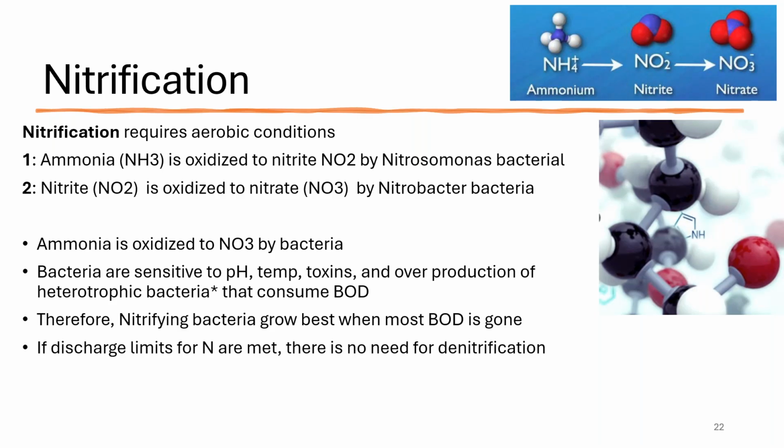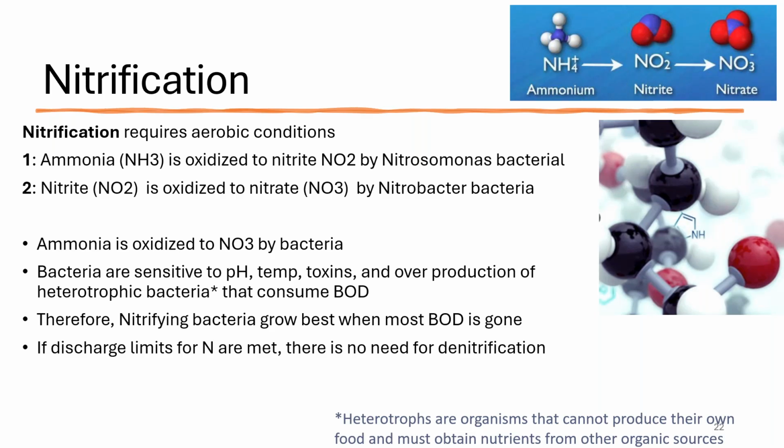And one final point is when you have a plant and you have an NPDES permit, there's going to be definite limitations on ammonia. And if you oxidize all the ammonia to nitrate and you meet the limitations for ammonia and nitrate, you're done. You don't need to denitrify. But if you have a permit that requires you to get rid of some of the nitrogen, then you would have to denitrify to actually remove nitrogen from the process.